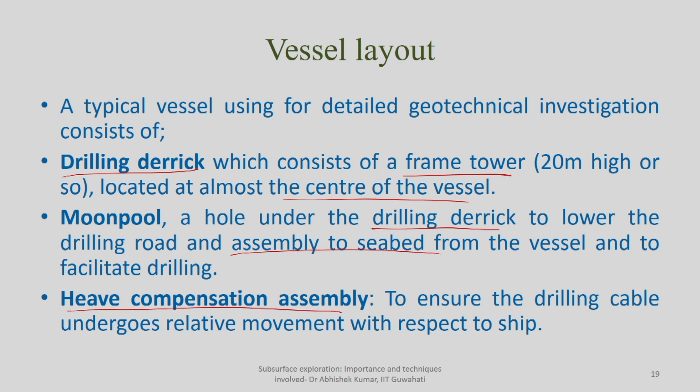A heave compensation assembly is provided so that the drilling has minimum effect from possible fluctuation in the water level. The drill cable must undergo relative movement with respect to the ship, because the ship itself will have some movement or fluctuation. To have minimum disturbance to the drilling assembly, you have to provide heave compensation.